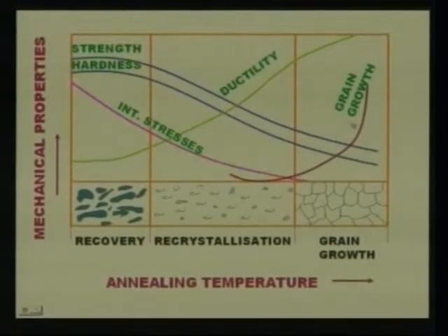Now you see the grain growth does not take place in recovery, but as grain growth proceeds, it first increases, slowly decreases, and again starts increasing, therefore the crystal size increases. Therefore after recrystallization, if you increase the temperature, it is disadvantageous in many applications. So this is the mechanical properties versus annealing temperature.